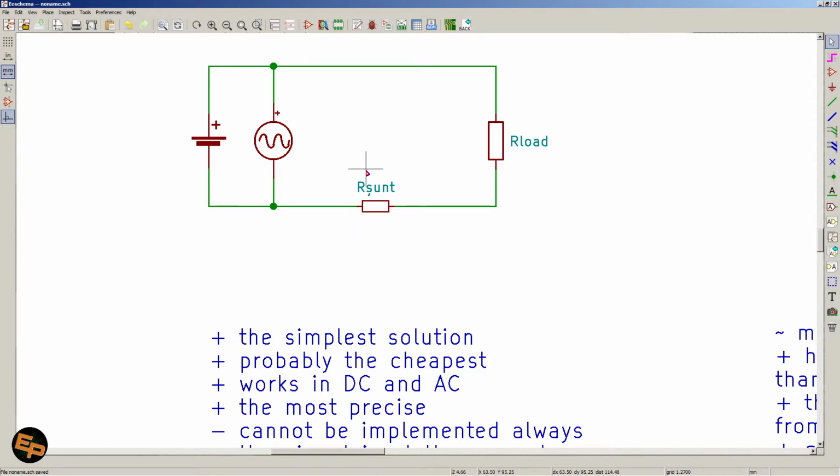First, because maybe the voltage on the load will drop a bit too much, because the entire voltage will not be applied only to the load but to the shunt resistor as well. The higher the current, the more of this voltage is being kept by the shunt resistor, so the less voltage appears on the load, and depending on the load, that might be a problem.